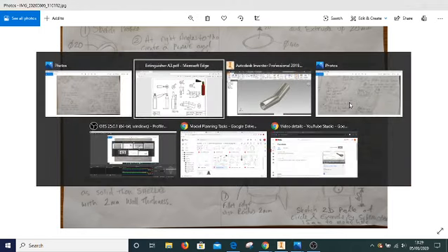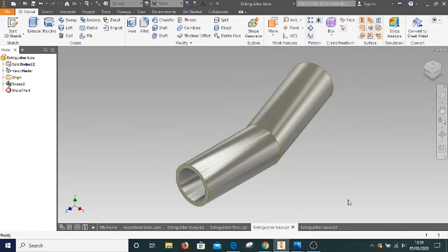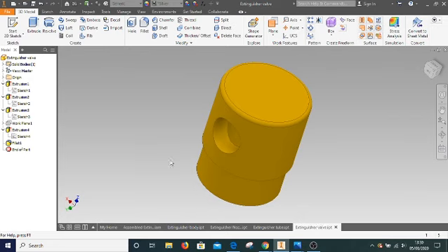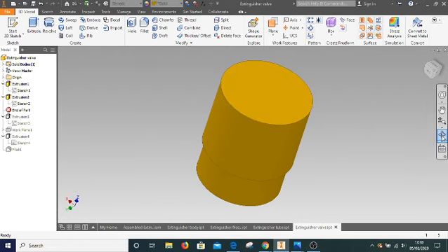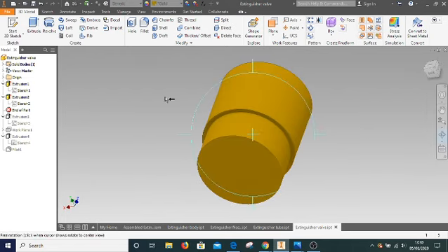Let's go to Inventor for our last time. Over here we're looking at the valve, and here we have the end of part marker. I'll take this up. So our first extrusion was that bottom part. Remember, I created a circle on top of this and then extruded that up, which gives us that. I'll turn it round and show what happens next. We were going to create the hole through the base. Take my end of part marker down, and there's a hole created there, 30mm diameter, going up into the shape by 50.